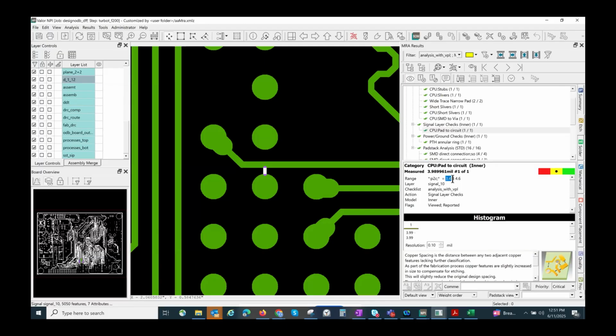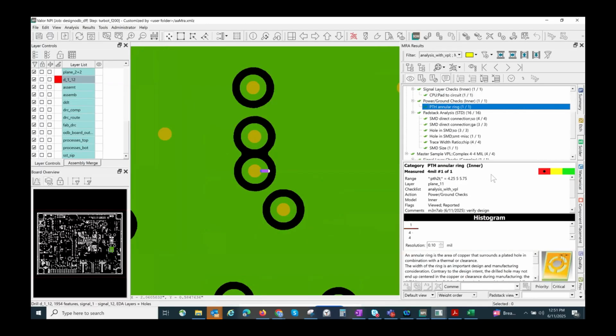So in the setup of the constraints, I set the nominal value, the yellow, and then I set a tolerance. By default it is plus or minus 15%, but I can adjust the tolerance, or I can set specific values for the red, yellow, and green if necessary. It has all the flexibility on that matter, but I just wanted to explain that to give you the overview.